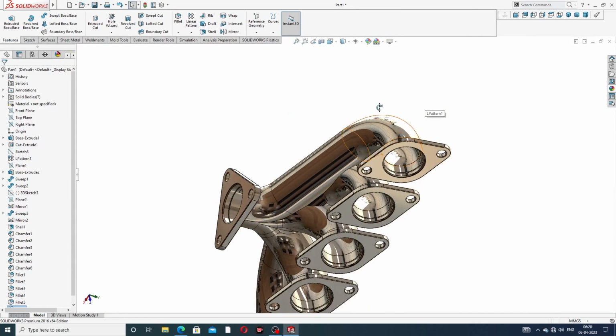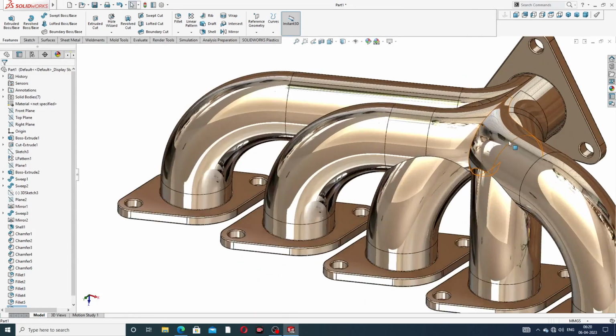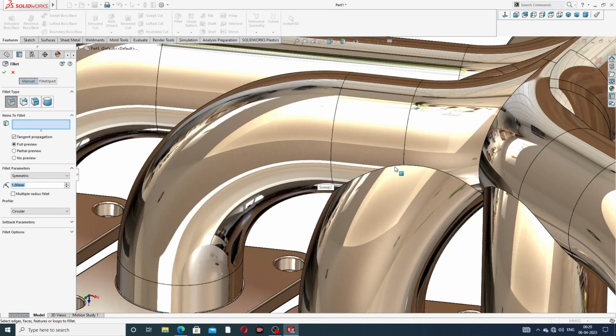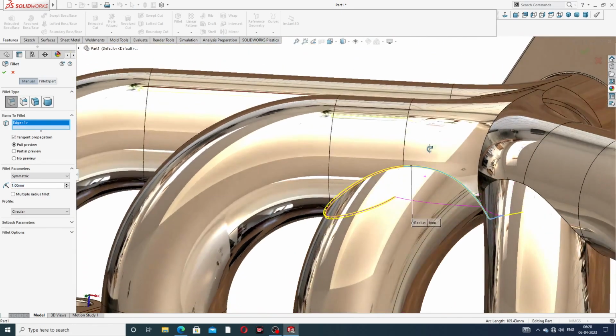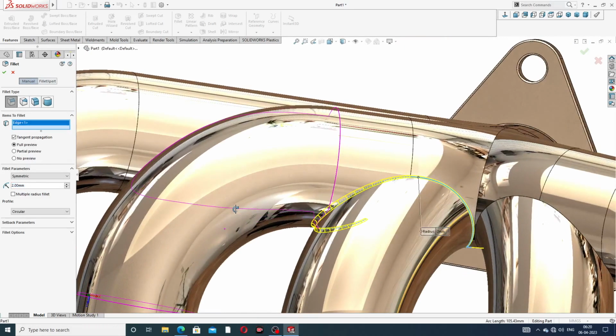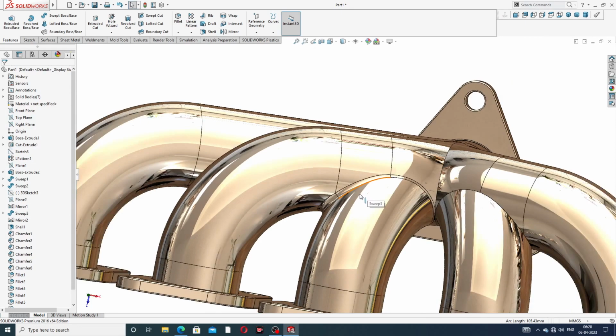Okay, all is perfect and correct. And also a fillet is used here, click this line, this 1 millimeter, and also select 2 millimeter. And okay, this is a 3 millimeter increase, and also this is a 4 millimeter, and click OK. Then some, very nice looking here.